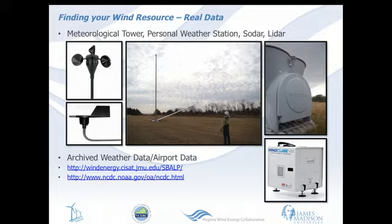This picture right here is a SODAR unit, and the one below it is a LiDAR unit. These are new remote sensing devices that have come out, and the top one is able to measure wind speed and direction data via sound waves, and the LiDAR uses a laser. The benefit of these is that these units are much smaller than an 80-foot tower. You can't really tell from the picture, but the SODAR unit is about as tall as me, maybe a little taller. It's just a big box, and the LiDARs are even smaller, a little bigger than maybe a briefcase, depending on which one you're using.